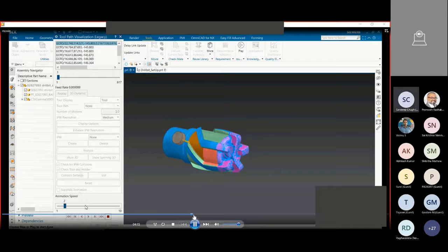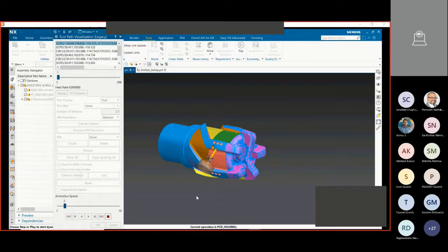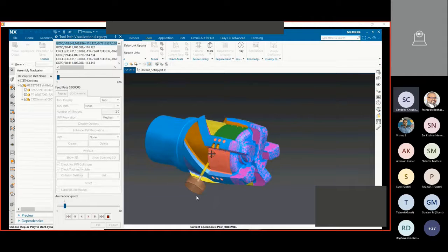Same 4-axis mill rotary. And once the flutes are finished, then we can shift to the carbide drilling, PDC cutter drilling, normal drilling, and you can pick all the drills together. You just need to create the windows and everything will be picked. Need not pick one by one. Once picked, then you can change the sequence as desired.